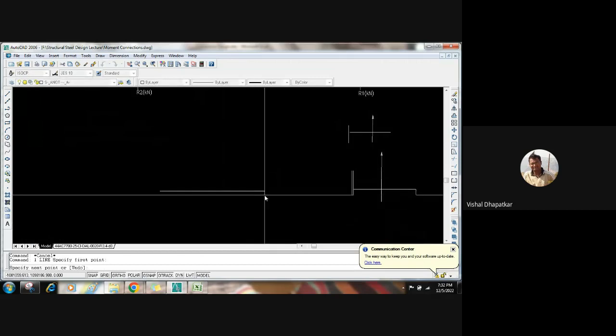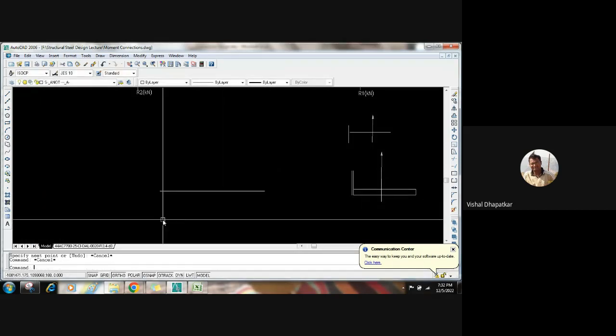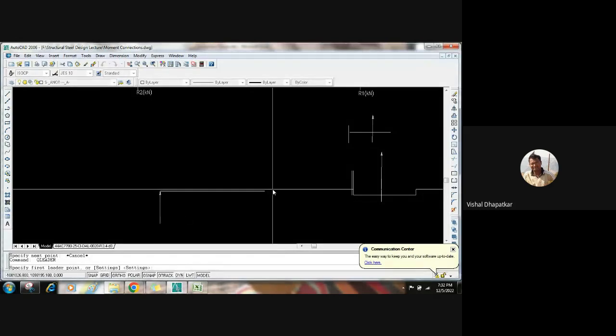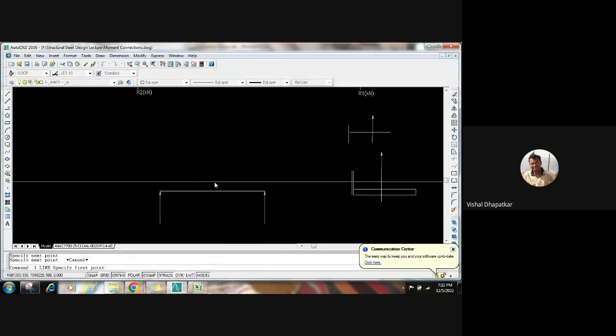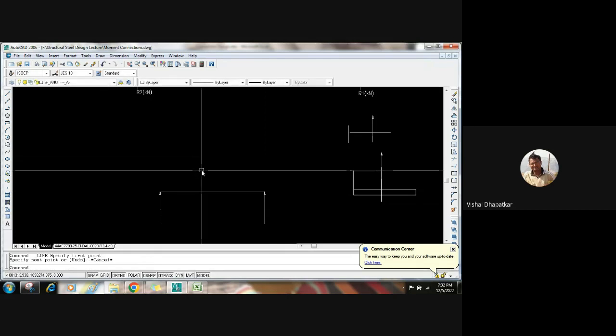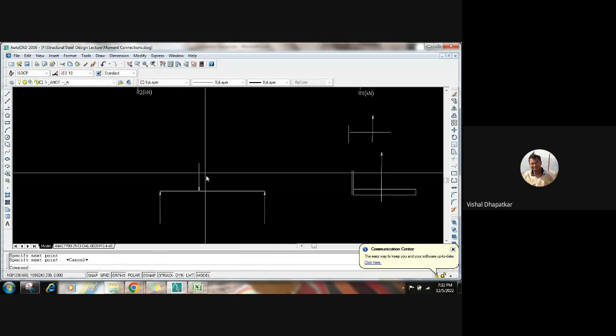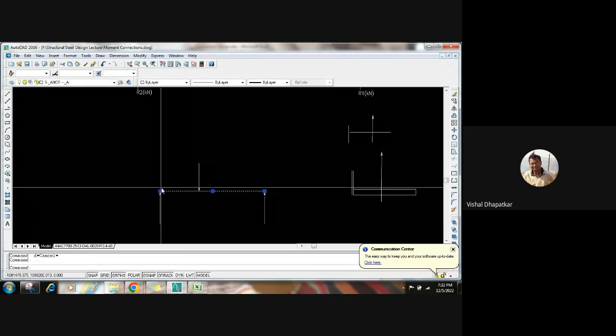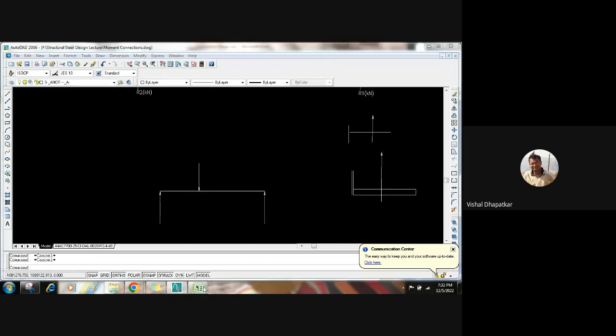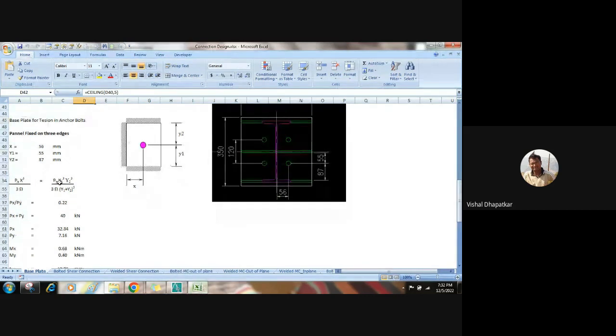So the other case is like this. We have a beam here. It is fixed at both ends, and somewhere the load is acting at this location. So this is distance A, this is distance B, for which we have to calculate the deflection. For a beam where the load is acting at an intermediate distance, the deflection is P A cube B cube divided by 3 E I into (A plus B) cube. You can find this expression in your second year book also.